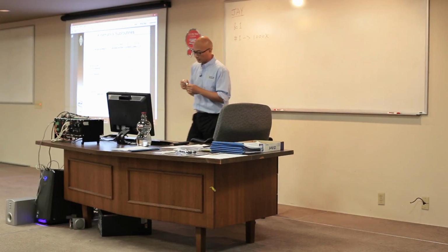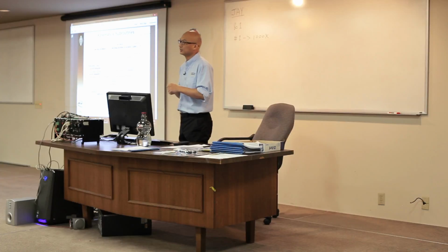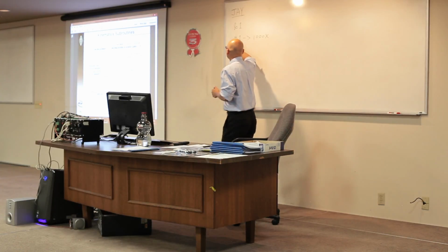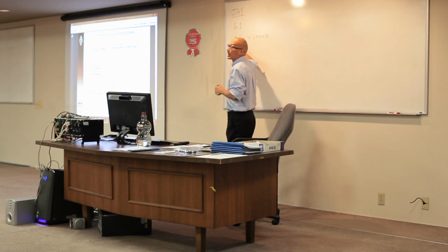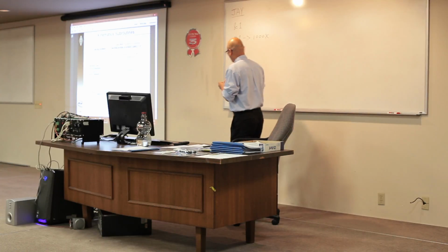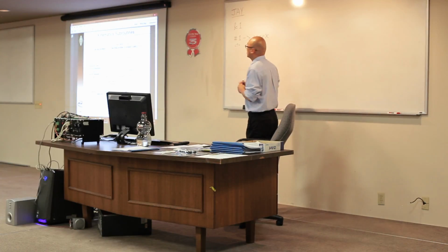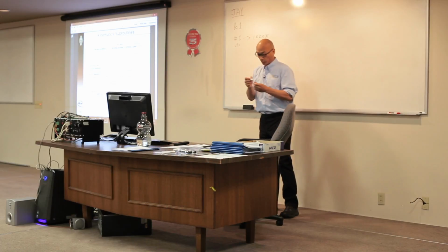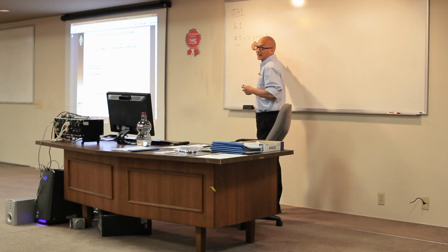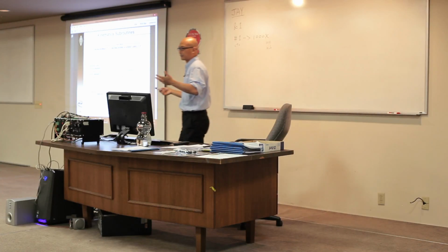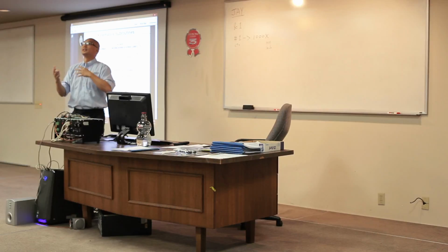Something like this. This is what we call axis definition, and there's a linear relationship between the motor and the axis you define. Usually the unit on the motor side is counts. On the axis side it is user unit, might be millimeter or inches or whatever, okay? So this is the scale factor between the motor counts and the user unit you are going to use, okay? That's basically the idea.